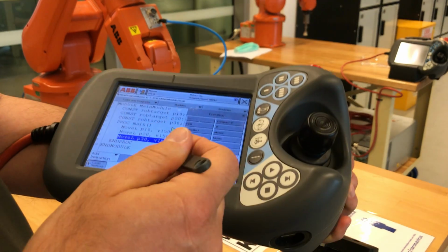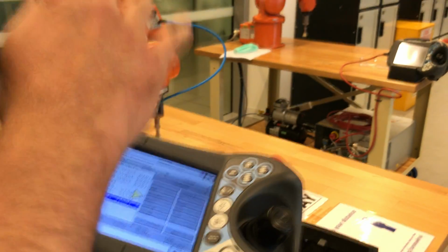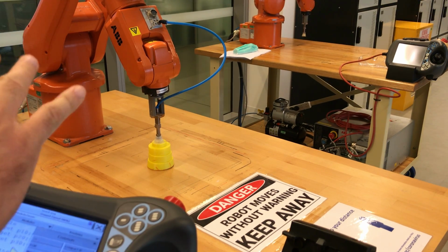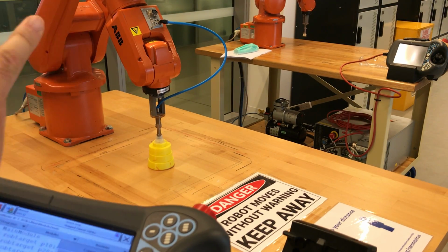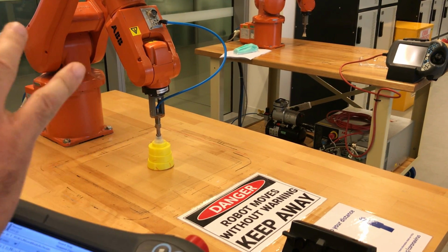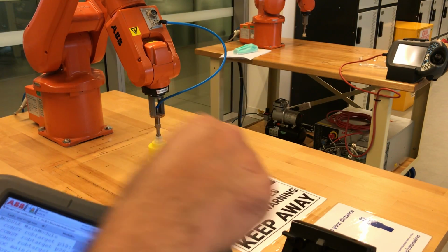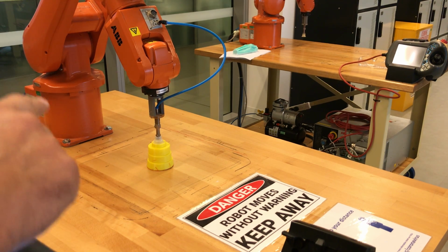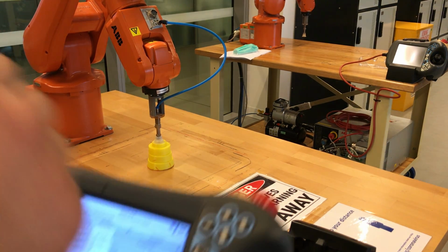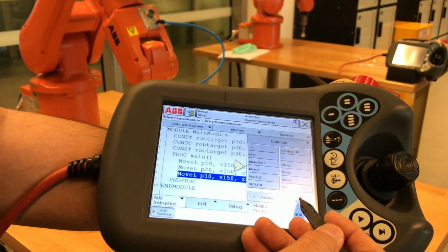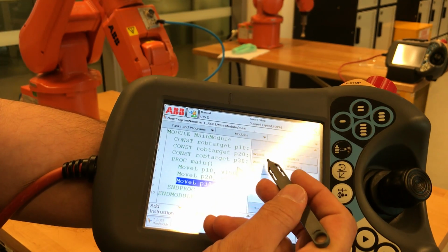Okay, now what we need to do is hold the part and take it up. To do that, we need to wait for at least 5 seconds before we hold the part. Otherwise, it's going to be something like hitting the part and going up, so there will be no time for the pressure to hold the part in this movement. To do that, we need to add a waiting time. So, wait time.